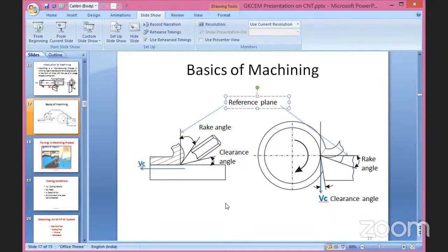So this is very, very important because the higher the positive rake angle, mind that forces will be reduced. That is the thumb rule. Okay. So suitable rake angles are used in different machining processes, and mind that in most ceramic cutting tools, we are using negative rake angles, where force requirement will be slightly higher, but the cross section of that particular cutting tool will be more, so the heat conduction area will be more if it is conductive in nature. And also you can use double the number of edges of a particular cutting tool insert. That is very important.